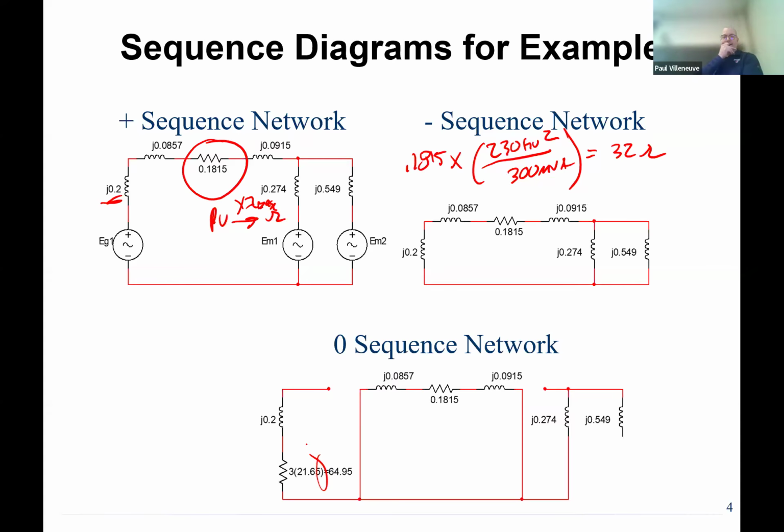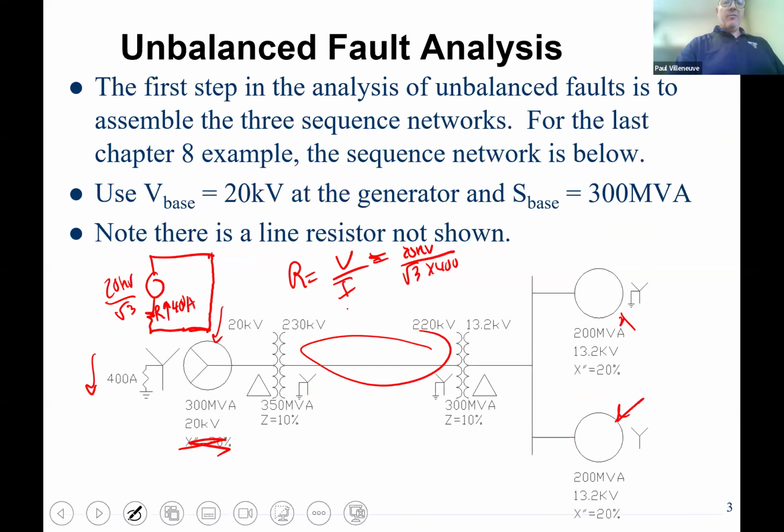Which resistance do you mean, the line? That's the resistance of the line from the generator to the first customer. Nope, that's between the two transformers. This impedance here and here, those are the two transformer impedances. So then what's that? That's the transmission line. That is the line impedance right here, connecting the two transformers, because they're not going to be in close proximity to each other. The likelihood that your load is close to your step-down transformer, or your generator is close to your step-up transformer, is pretty high, but the transmission line might be 50 miles long. So it would have some impedance associated with it.